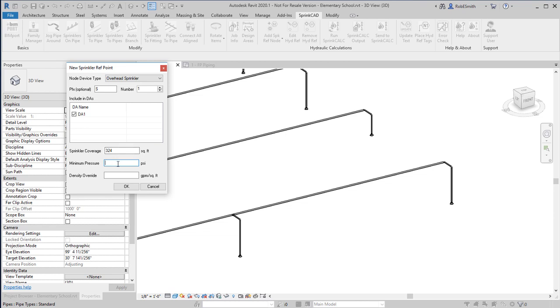However, the cut sheet for this particular sprinkler head does require 33 GPM. So I could have put 330 here, but I also note that the minimum pressure, according to the manufacturer, is 8.7 psi on the 11.2 K-factor head. So I'll just put in the minimum pressure. The program will balance these two and it'll say which is the more demanding condition.